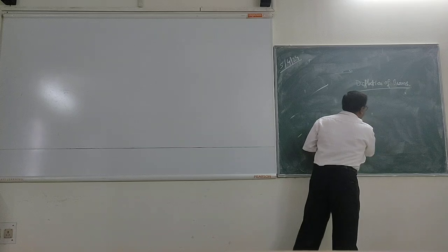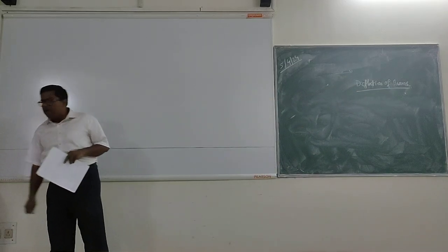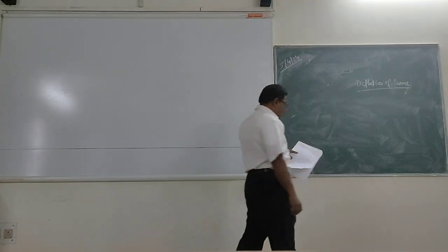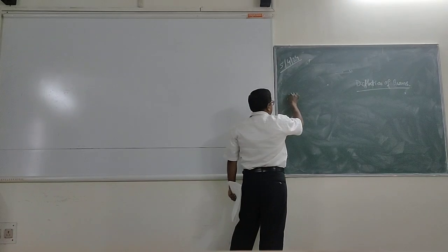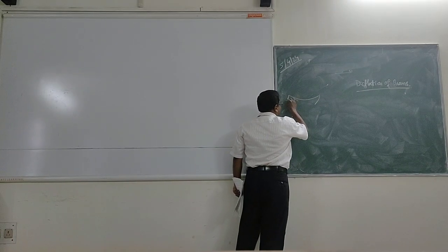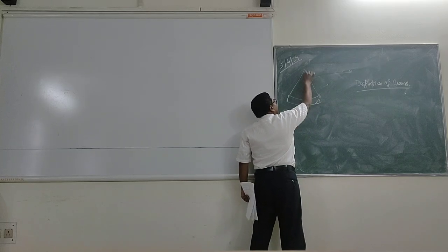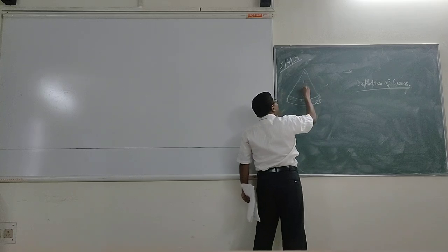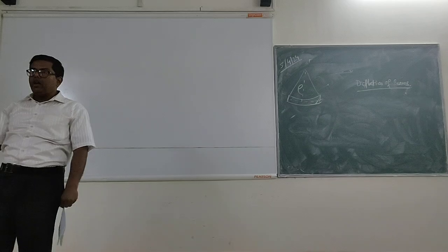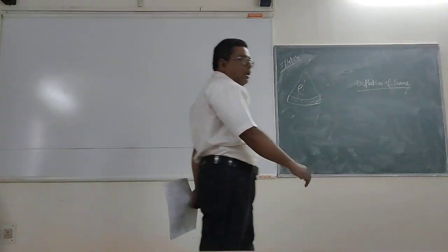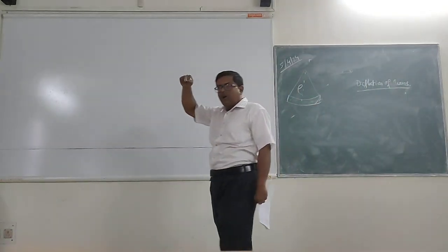So you have by now learned about the beam bending theory, and from that we have seen the elastic curve, that the beam is bending downward. So if there is a bending downward, and I do this here, then I get a rho over here. So the curvature of the deflected shape of the beam is 1 by rho.